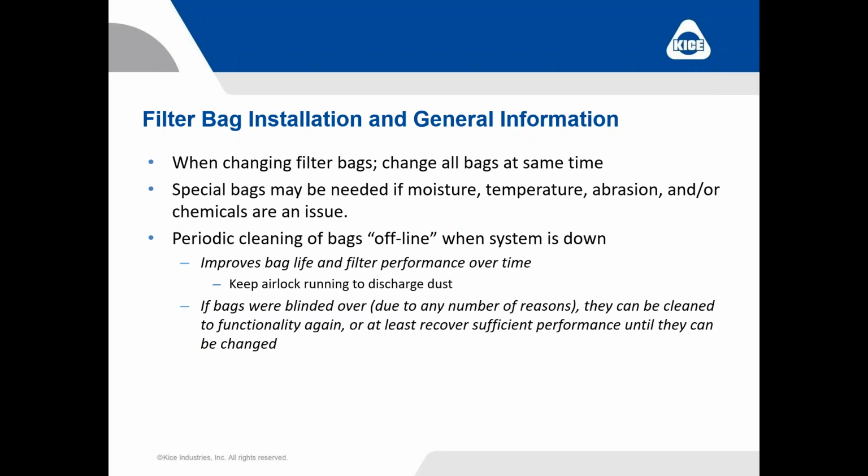There are special bags available. We talked about abrasion a minute ago. High temperatures sometimes require special filter bags. High moisture applications, corrosive gas applications, chemicals. Some of these may require special bags. So if this is the type of process that you were involved in, if it's not just your everyday run-of-the-mill dust, make sure to talk to your filter bag manufacturer about that. Make sure that they're aware of that so they can work to get you the proper bags for your application.